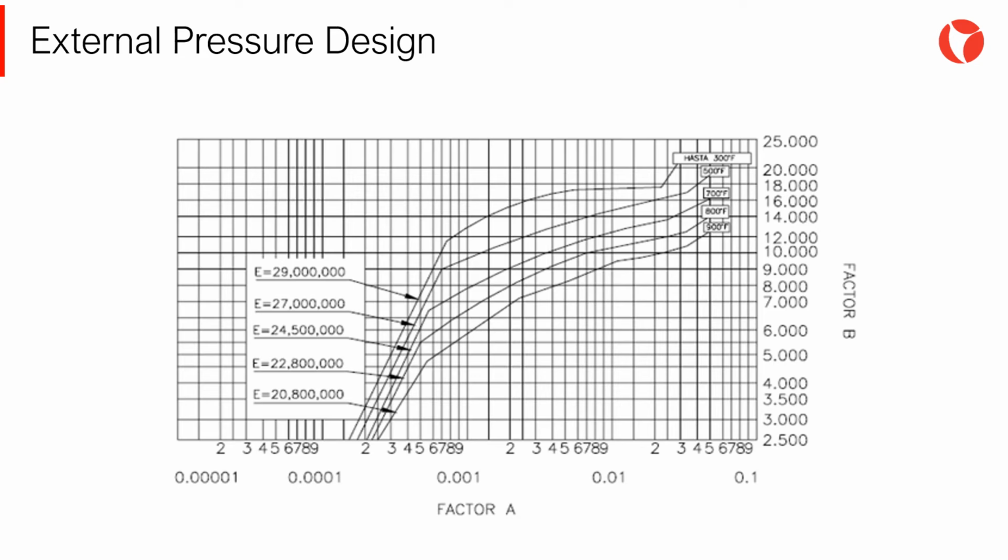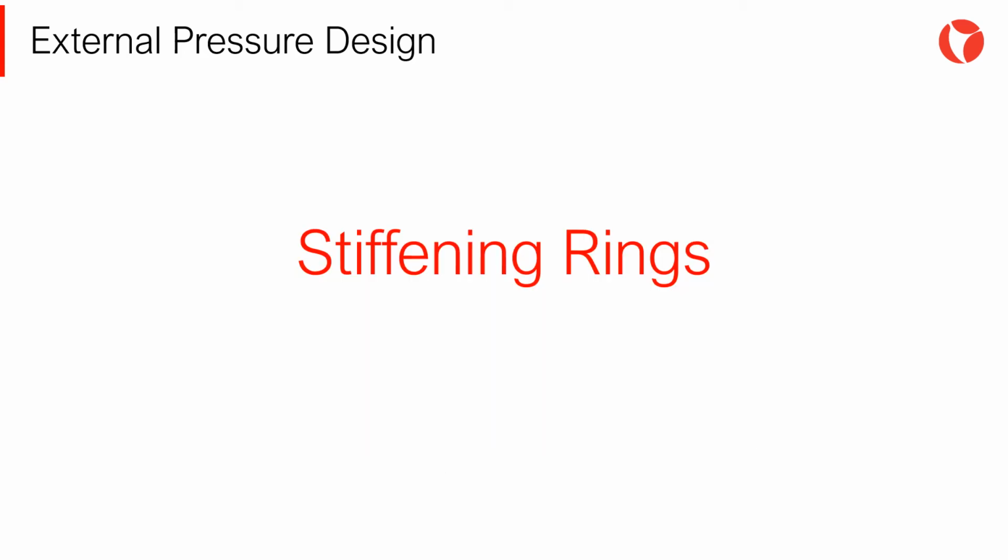If the amount of external pressure that the vessel can bear is lower than the actual external pressure, the thickness of the vessel has to be increased or the geometry of the vessel changed. Obviously, the diameter and length of the vessel cannot be changed, but the distance between lines of supports can be changed. Increasing the shell thickness to withstand the external pressure requirements won't be always economical.